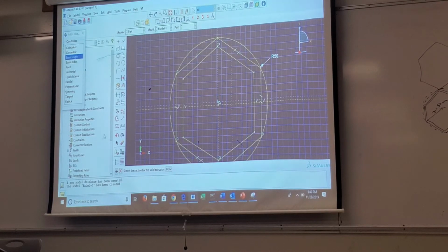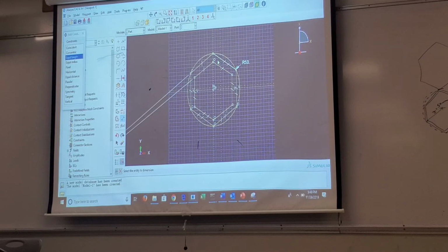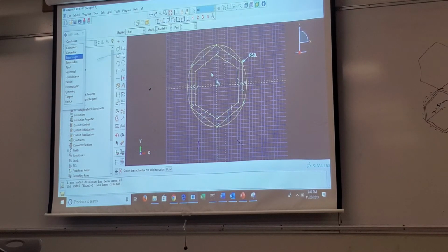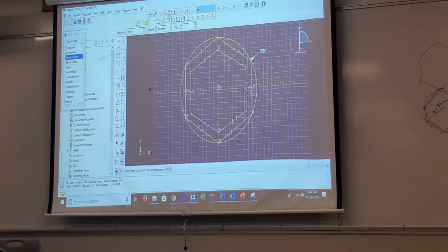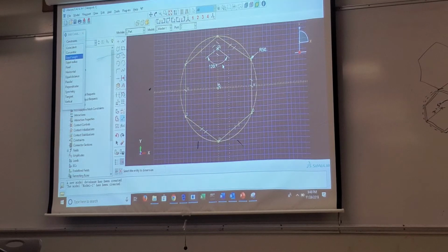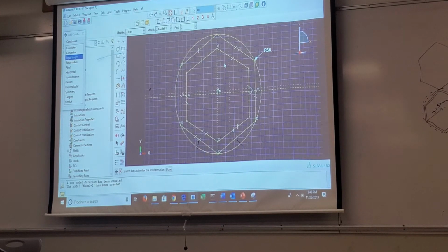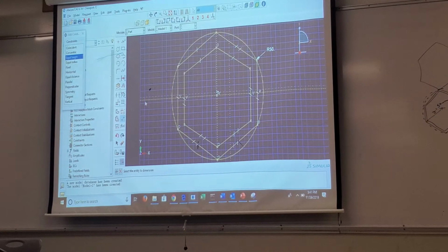And then I set that as equal length. Let me see if it allows me to do that. Okay. And then I decide it to have a specific distance, which is, let's say, 1.5 millimeters. Yeah, degrees have to be restricted first. What was the spacing? 1.5 millimeters. Yeah, then we do lines, make a hexagon. Then just roughly make a hexagon.